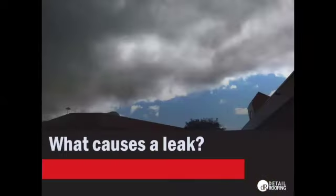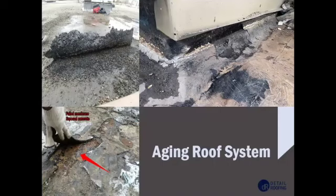So what causes a leak? An aging roof system that is failing is definitely one of the main causes of roof leaks. In these two photos, the top left and bottom right, both membrane systems are underneath an inverted roof system.